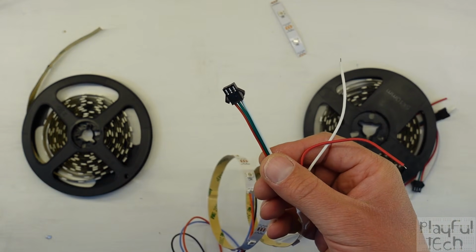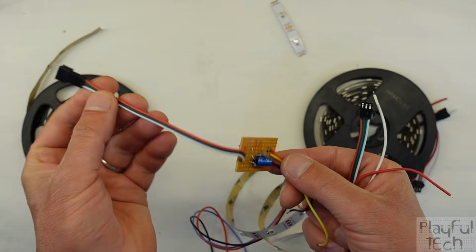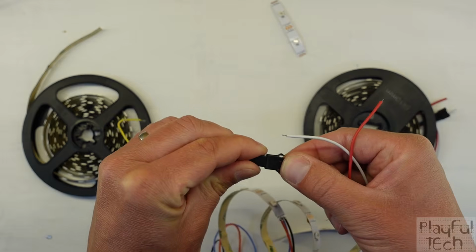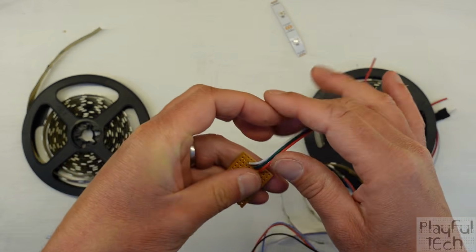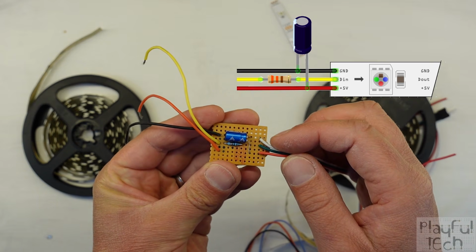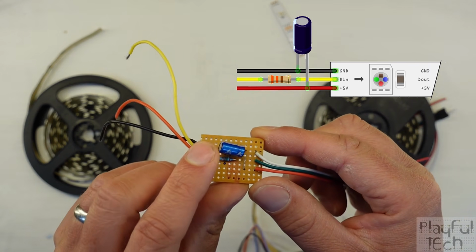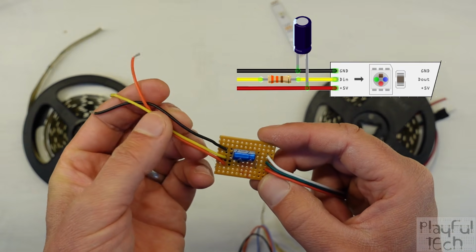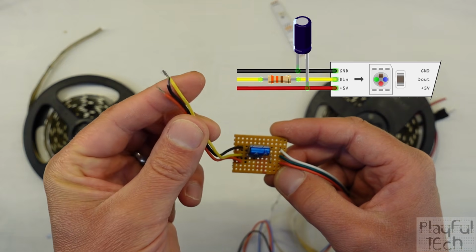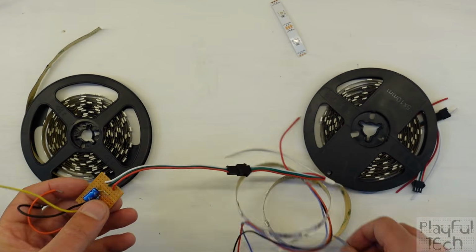Now, most microprocessors can't connect directly to a JST connector, so what I generally do is make a little adapter board like this. This has a female JST connector which will connect to the LED strip, and then it also has 2 components on the board. There's a 470 microfarad capacitor here, and then underneath there's also a 330 ohm resistor in series on the data line. Now, you might find that your LED strip will work fine without these additional components, but it's good practice to add them. And then I've just got the 3 wires here, which I can connect directly to the Arduino.